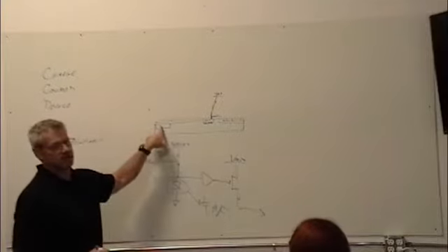I took a saw and I cut that silicon slug into a wafer, right? And so if I've got the silicon, this is monocrystalline. It is a single crystal. It's not like martensite steel or whatever, when you heat up, and it gets all these different crystal grains that grow together. They take great pains to make that one crystal. That whole great big slug, when you see the pictures of them pull a silicon ingot out, it is one crystal. It has no crystal boundaries in it. It is, seriously, one crystal.